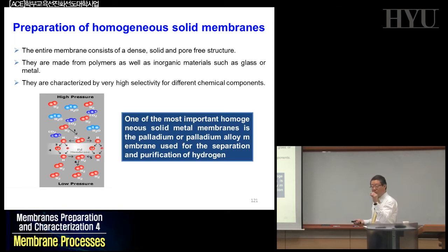The thickness of this palladium will determine the economics of your membrane, because the thick palladium membrane, of course, will be very expensive. So thinner is better. Thinner and more permeable will be the ultimate goal of your palladium membrane production, of course. And there are a large number of groups, as I told you already, particularly Professor Ma at Worcester Polytech, who is the pioneer in the palladium membrane.